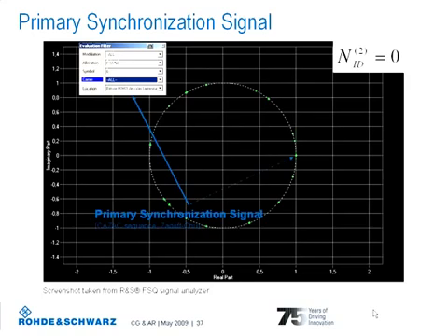Subcarrier is a good keyword. In the frequency domain, the primary synchronization signal occupies 62 out of 72 reserved subcarriers around the unused DC subcarrier, which corresponds to the carrier frequency in the downlink. The remaining 10 subcarriers, 5 left-hand side and 5 right-hand side, are not used for any transmission. We can call them guard subcarriers.